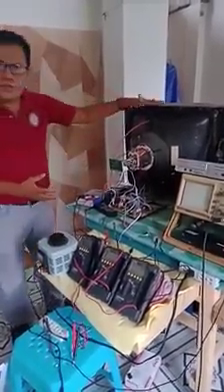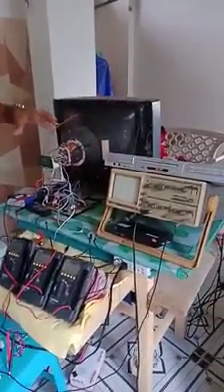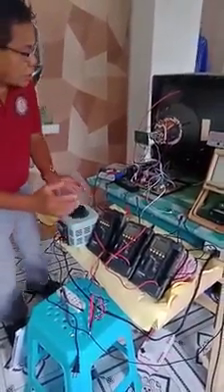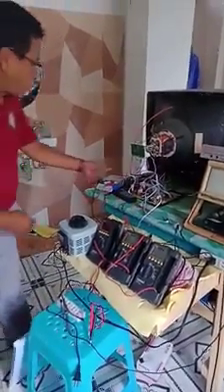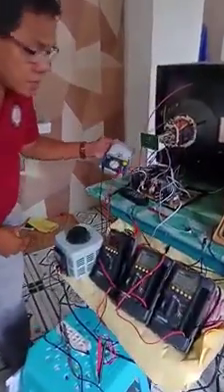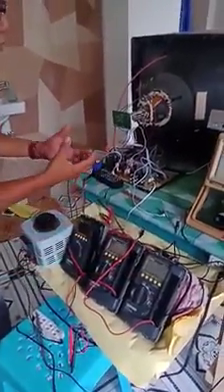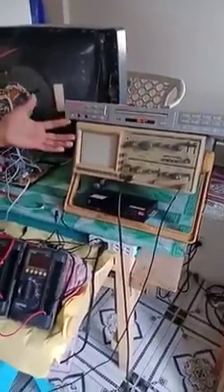With this activity class, we are in dire need of the following equipment and test instruments. For the equipment, of course, we need a TV receiver, a DVD player, which is the source of the picture and sound signal for the TV receiver, and a variac transformer, or the so-called variable AC transformer, that will provide different levels of AC voltages to the TV receivers. And for the test instruments, class, of course, we need this analog multimeter, the digital multimeters, which are needed for the measurement of different voltages of the circuit, and this oscilloscope.